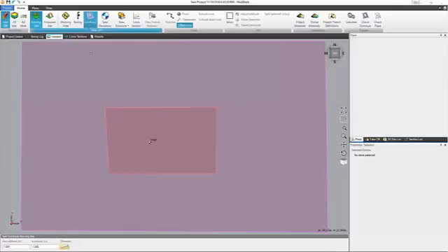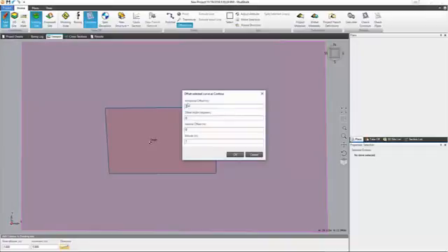If we pick contours, say, and we want to create an offset line, offset from this boundary of this structure here, we can pick the boundary and we've got these options available. So let's say we're going to offset it by 1 meter. And we've got these other options where we can put an offset angle in, a vertical offset and altitude, and they're all interlinked. So if I put in minus 45 here, you can see that the vertical offset becomes -1 and the altitude becomes 0.